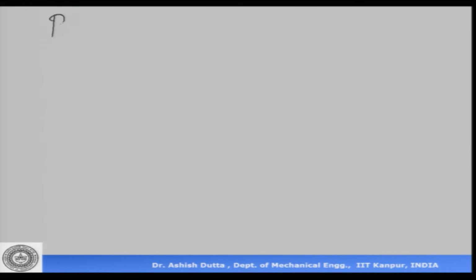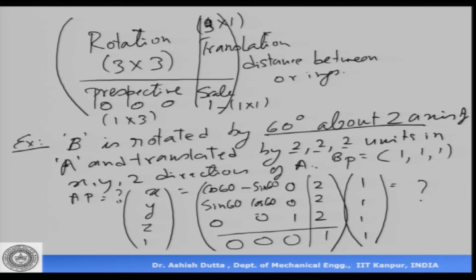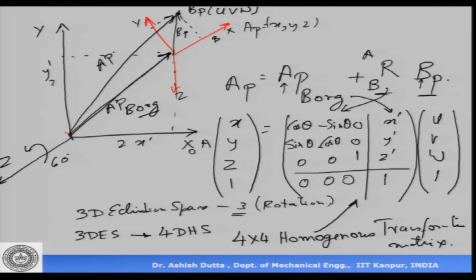So, we have seen that the inverse of the rotation matrix is equal to its transpose, because it is a proper orthonormal matrix. Now, what is the inverse of the homogeneous transformation matrix? If you can imagine a little bit here. How did this frame go here? This frame rotated and then it translated, right, that is how it went there.